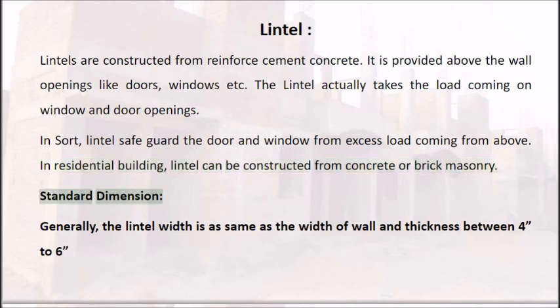Standard dimension. Generally, the lintel width is the same as the width of the wall and thickness between 4 to 6 inches.